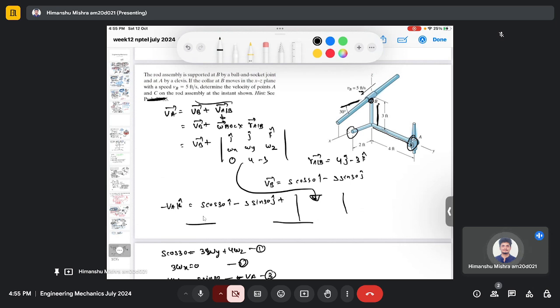Right? So you can see this joint Y is a constant. So this point A can move up and down. Point A is only having translation motion. It cannot rotate because there is a joint provided here. So it can actually move upside and downside, but it cannot move left and right. It cannot move backward and forward also.